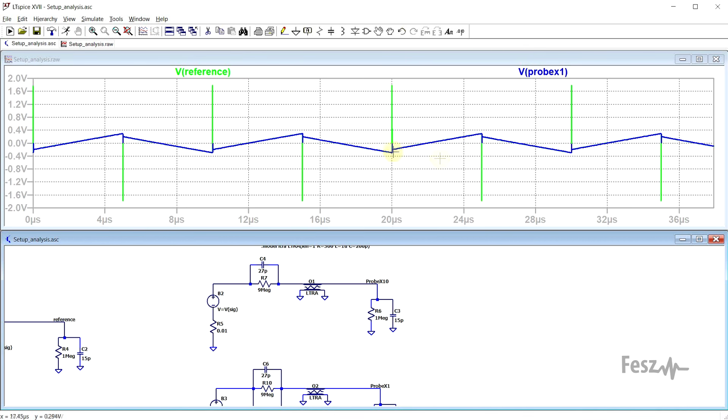On the other hand, if we look at the X1 probe and compare this to the reference, by overlapping the two, we can make two important observations. The exact ripple value is unattenuated. X1 simply means divide by 1, so it's the same value, but the noise is greatly reduced. So it's nowhere near the reference. So the X1 probe will preserve the low frequency content of the waveform, but not the high frequency content.